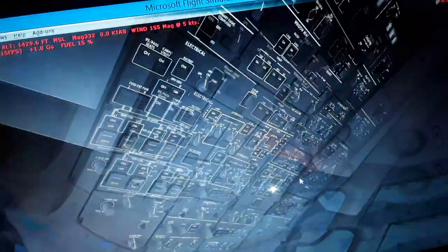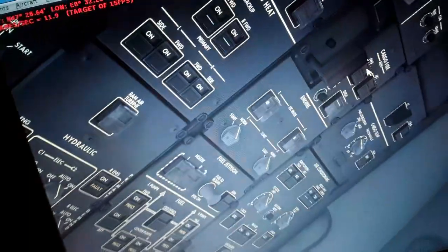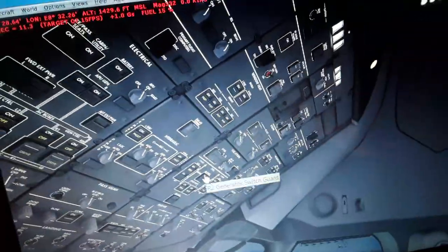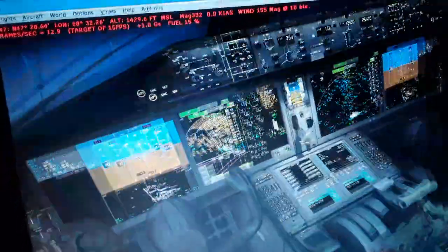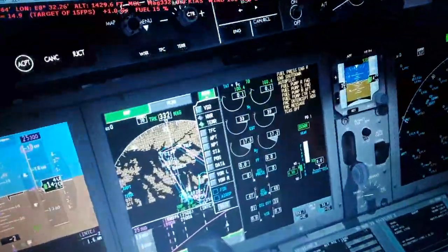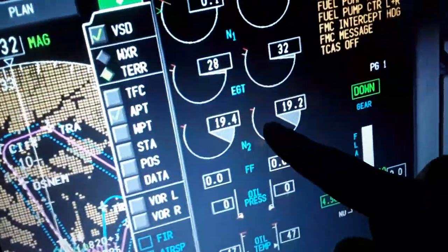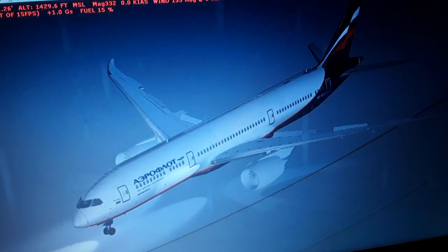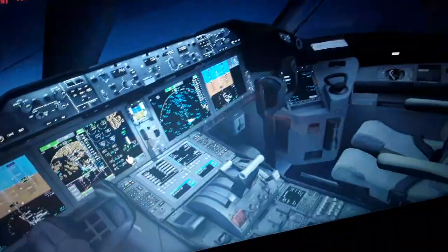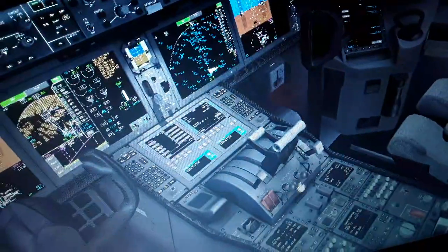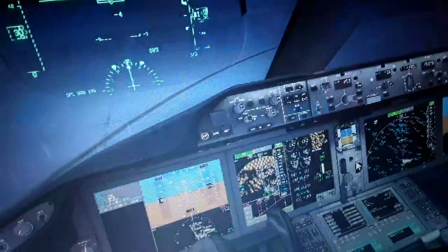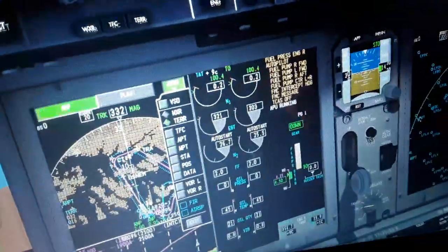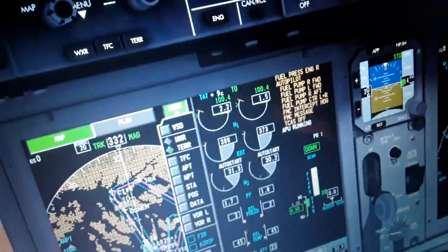We need to go to the overhead panel and set up both starters, auto start here in auto, left and right engine. You see the indications, their configuration in yellow with the switches. And now we're going to have pressurization, 19% of the N2, 20%, above 20%. We can feed both engines with fuel. So we turn both fuel controls on very quickly, as you see. This is a very fast engine auto start system.